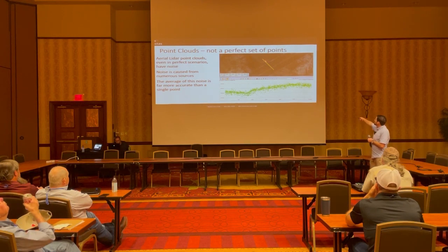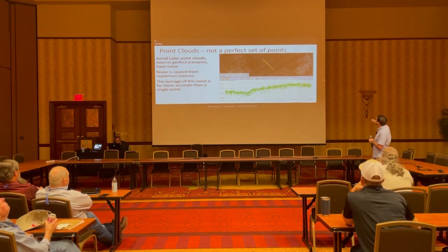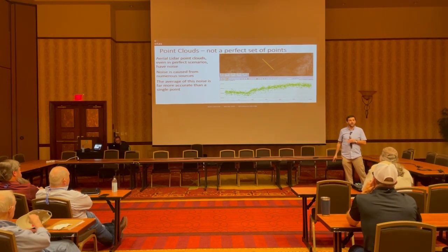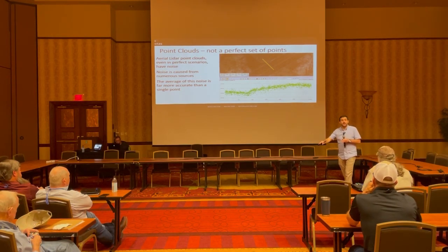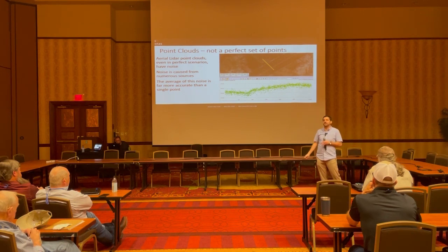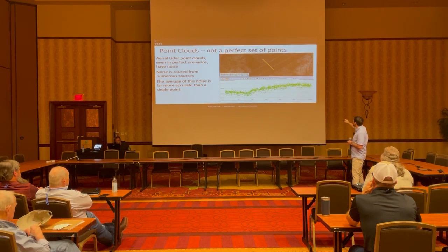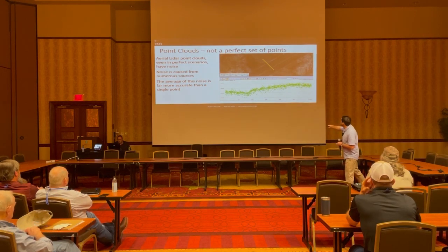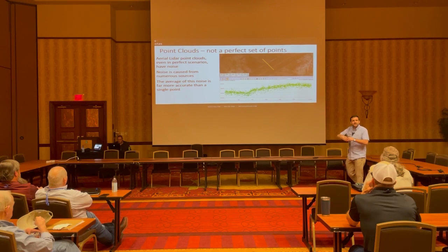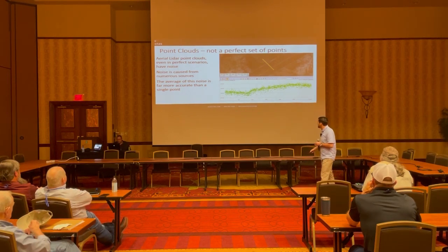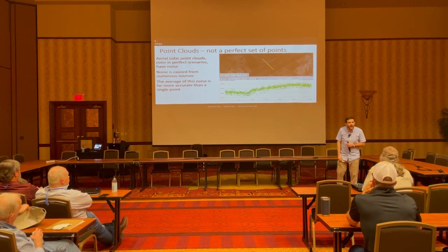So you can't quite tell in the imagery up there, but that's going to be a road, and this is the cross section of the road. So that is asphalt. Asphalt is hard. If you had perfect LiDAR, or honestly, if you had ground-based LiDAR that wasn't subject to the same noise as aerial LiDAR, you would see one really, really thin, perfect line of points as it goes down. That's into the gutter area, and that's up towards the crown of the road. But what you can see is there's this noise. It's a spread. It's a cloud. And the size of that cloud is actually like half a foot. It's kind of a lot.